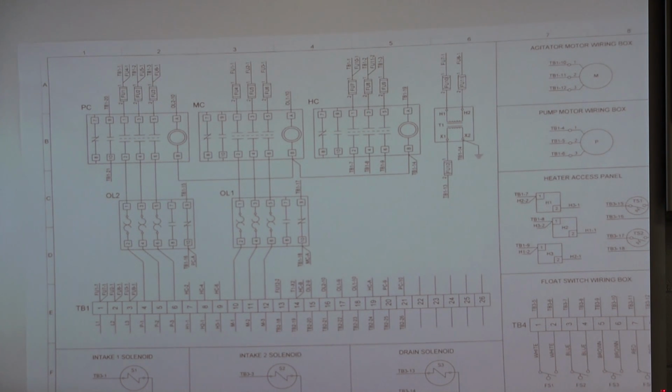Because that fire can spread from that motor to other parts of the equipment. So the overload relays simply monitor that motor, and if it starts pulling too much current, they'll shut the motor down, which might mean you can rebuild that motor and fix a problem with it, particularly if something is binding to the piece of equipment, before you burn up the motor. Secondly, it means you might not burn your facility down, which is another side benefit. So that's what overload relays in essence do.